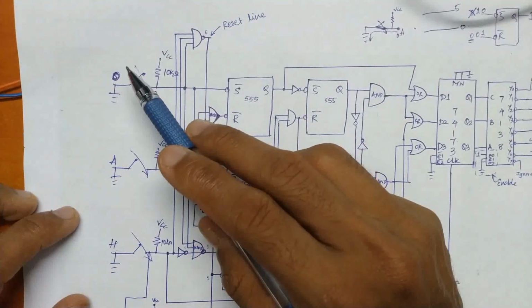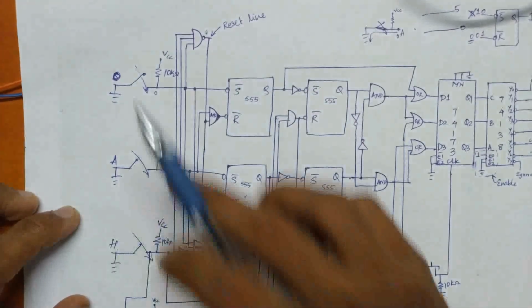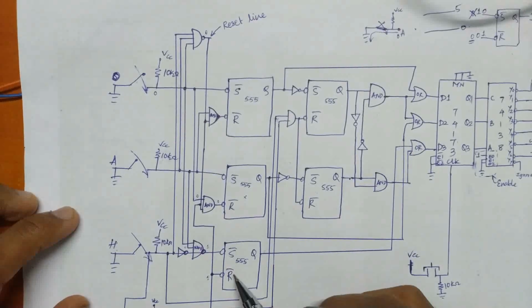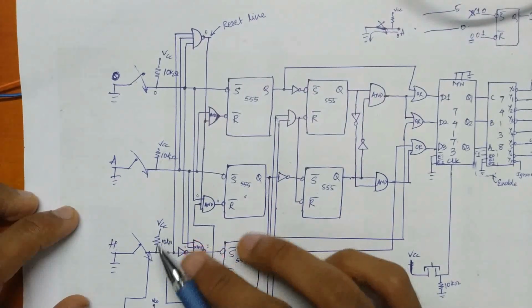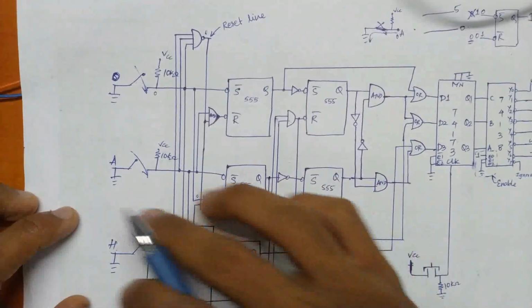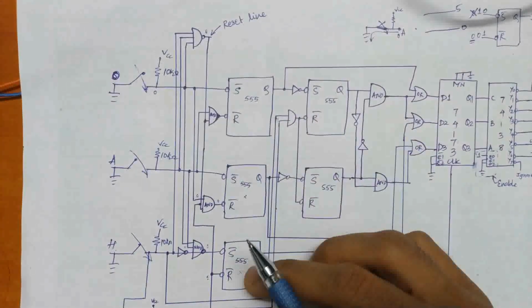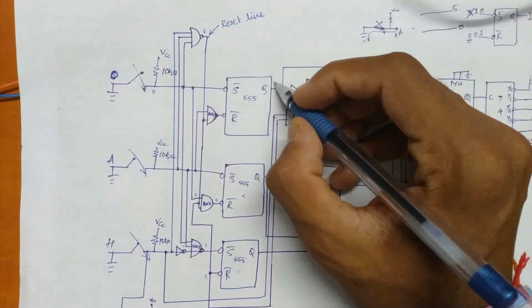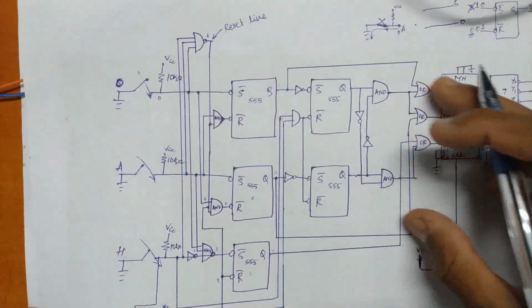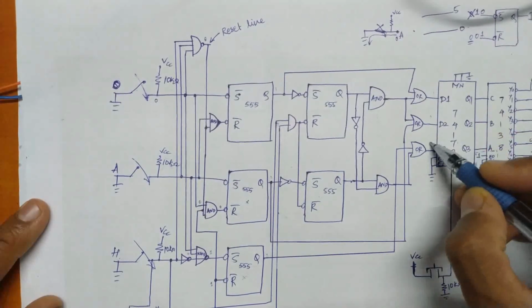So if I'm trying to get sine, then I'll just press opposite, and I'll press hypotenuse. Once I press opposite first, these ICs will be kind of disabled. This won't be disabled, but its input itself will be disabled. So it's like practically saying that this IC is disabled. So these two ICs will be disabled. So by clicking opposite and hypotenuse, I'll just get 1 0 0 as the output, and these outputs will be taken over here, and obviously eventually after all the combinational logic, I'll get 1 0 0 over here as well.